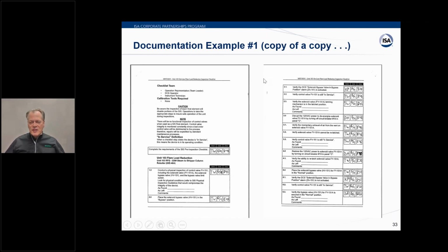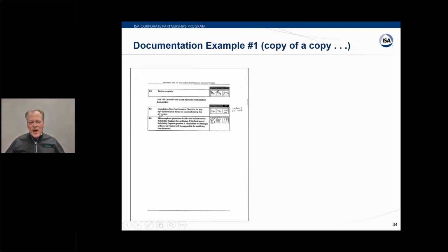So just pointing out some differences here. And then here's the final page. And look, here's a comment out in the margin because there really wasn't an allowance for it, and it actually says repair air leaks. This is great that the technician made a comment along these lines, but maybe this is sort of an as found and as left. So there was an air leak as found, and then they made this repair and as left it would pass. But maybe more information sure would be helpful here.